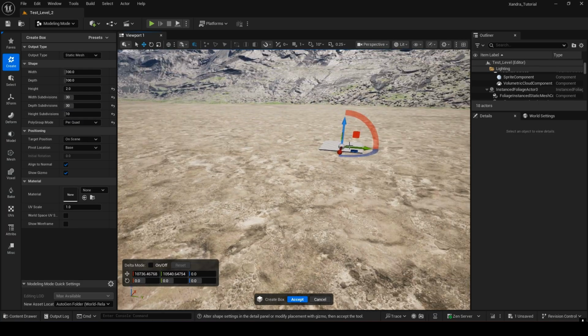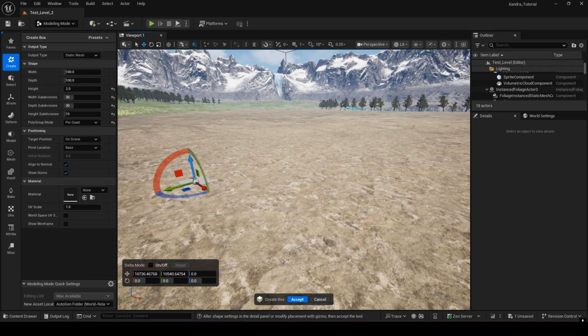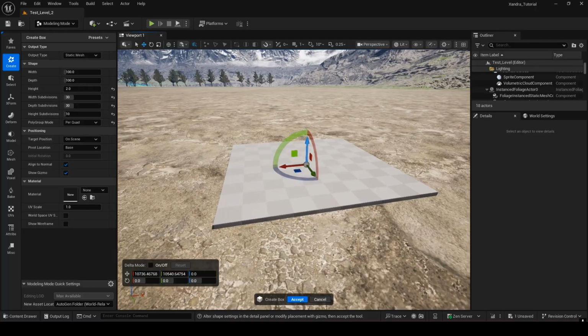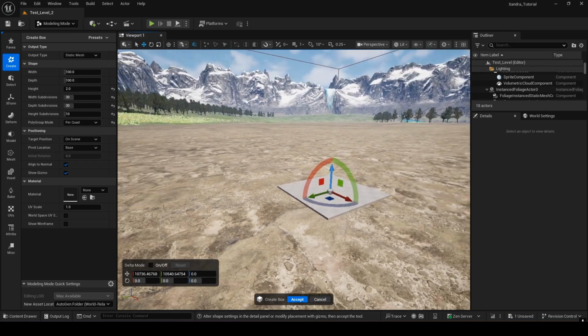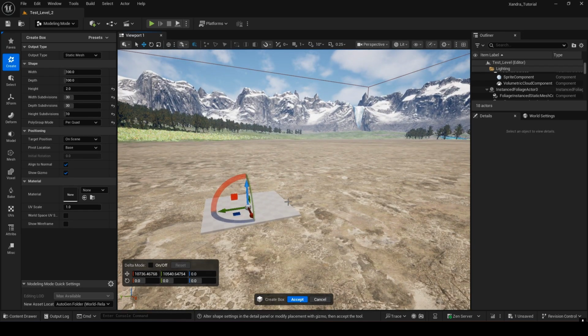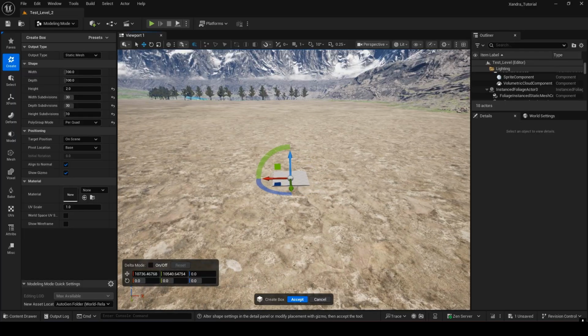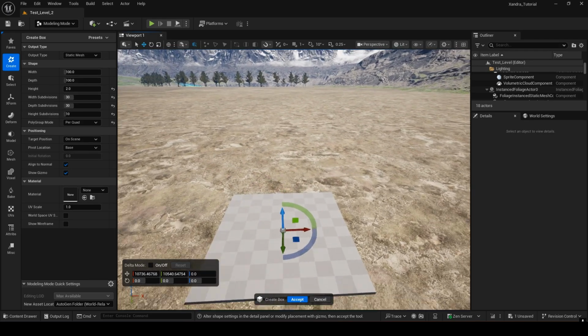That's for if I need the road to curve upwards, for example going up a bridge or up a hillside, and how smooth that upward transition needs to be. You don't generally need as many subdivisions for that. The reason is that roads in real life don't go 90 degrees up into the sky, so you don't need that smooth corner going up. It doesn't need that level of smoothness. If I was going up these hills in the back here, it's just a slight incline, so you're not really going to notice the lower level of subdivisions.